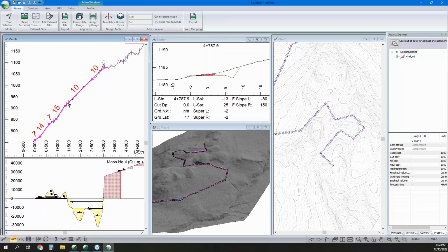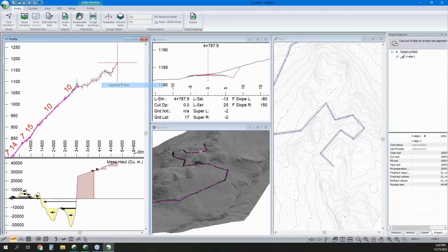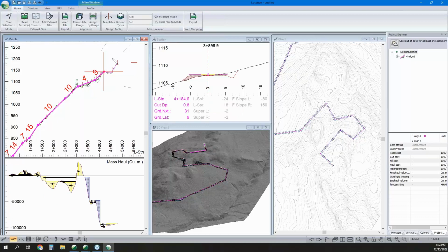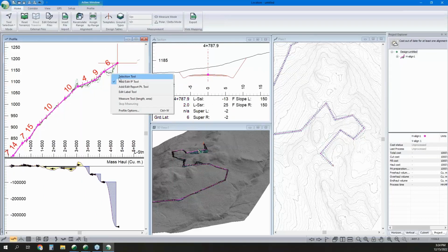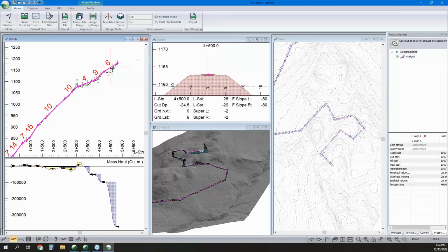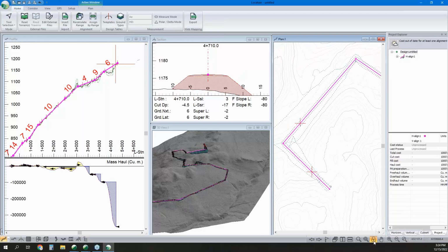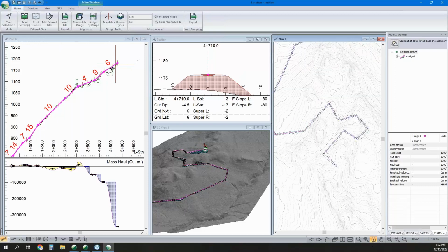So I'm looking at that. I don't see any obvious issues. Of course, I've got a really big cut there, but we'll iron that out here in a moment. I've got a massive fill there as well. So I'm just going to click there and see where am I at. And this scale is locked as well. So if I turn that off, we can see my cursor's right around there, and maybe it makes sense to pull that into the hillside.